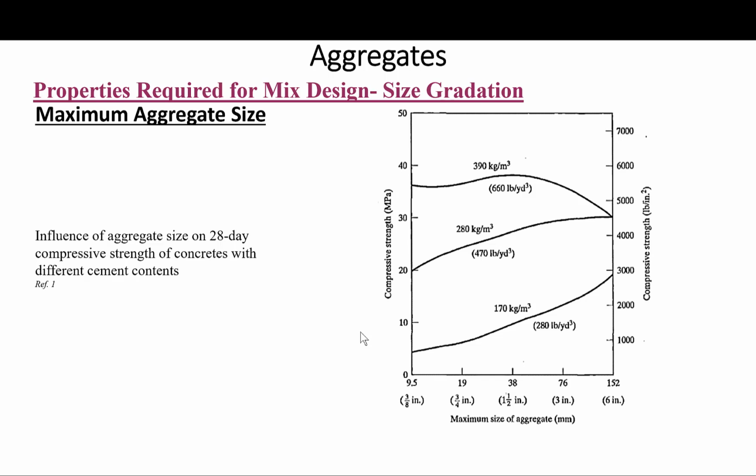As I said, with the larger aggregate size, increased internal stresses tend to lower the strength. And I said this is most noticeable in rich mixes with high cement proportion. So if the water-cement ratio is not lowered, the strength will drop with an increased maximum aggregate size.